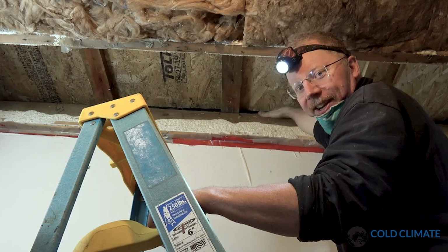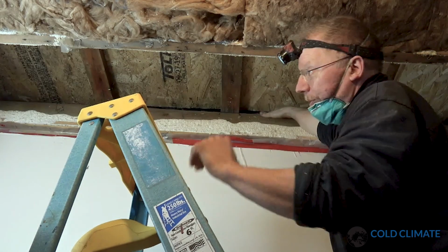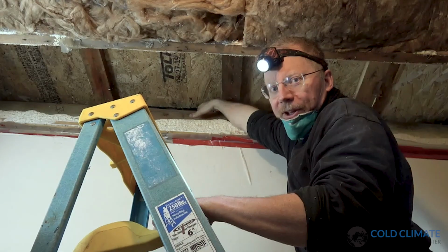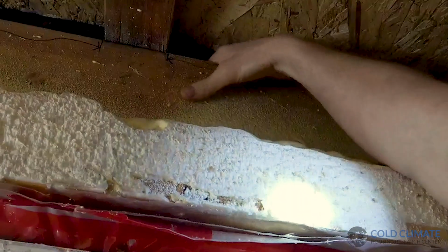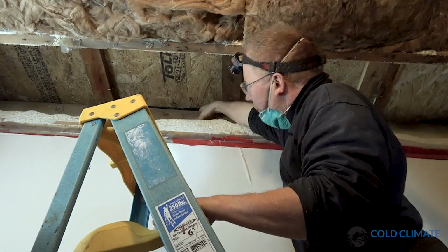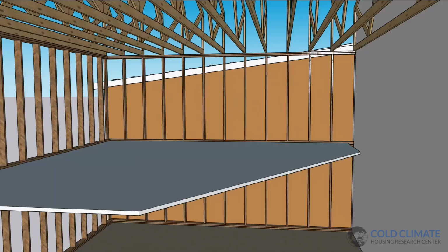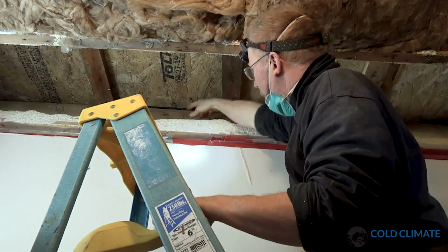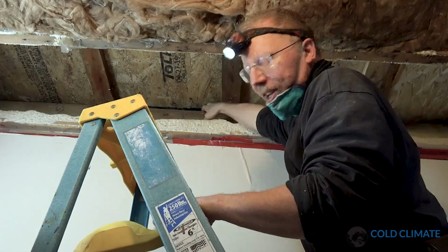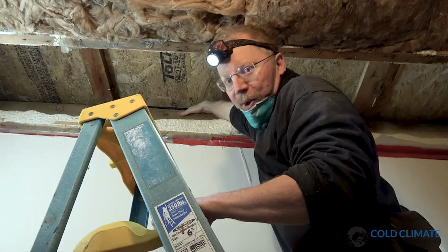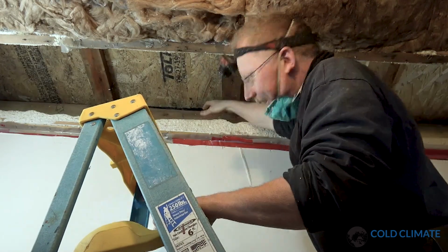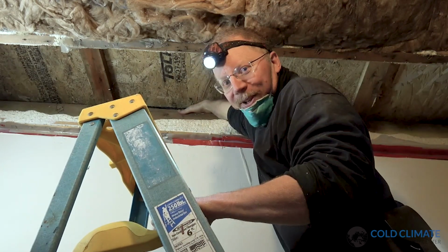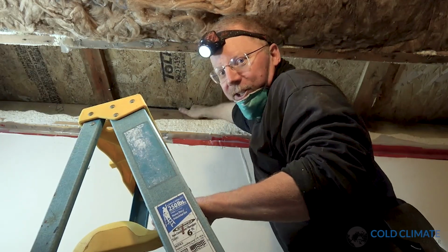Now we're back inside after running the fog machine, and we've removed the plastic from the closet ceiling. And this is one of the pathways that we suspected, air leakage pathways, and it's between the two walls, the wall of the addition and the old wall of the house. And last January, when the water problems first started, I marked these spots when we looked inside here, and I could reach over this rafter and the insulation was saturated. Even today, I can reach over this wall, over this rafter, and get into the space between the two walls, and that insulation is still wet.